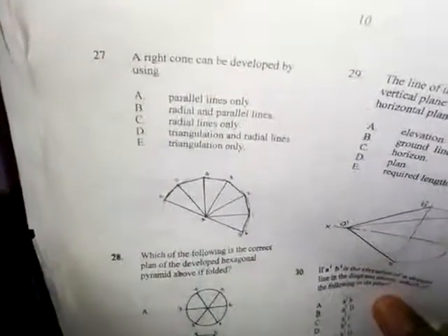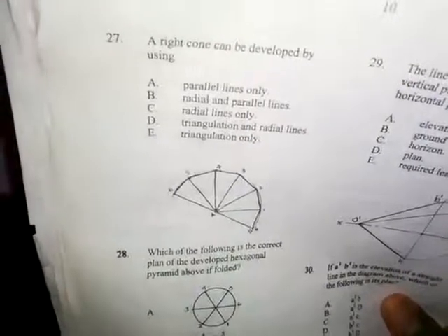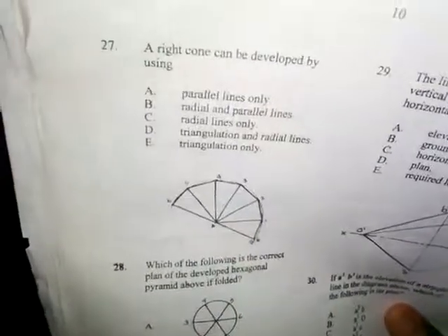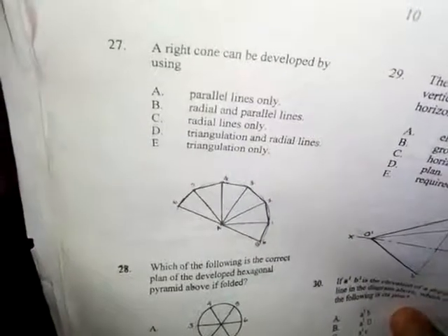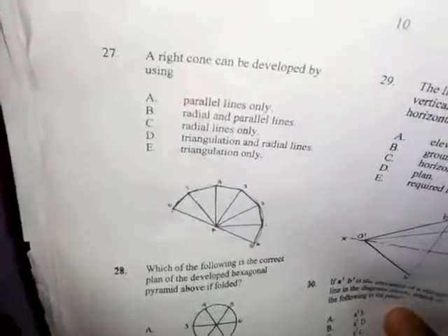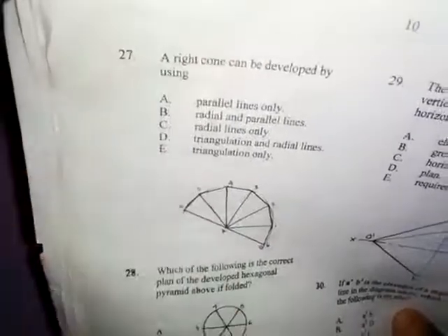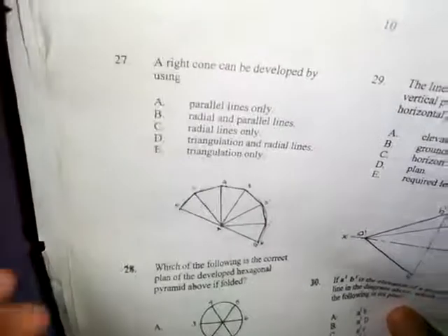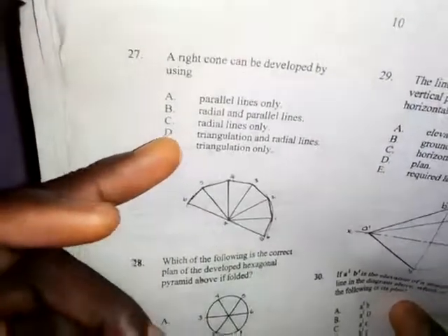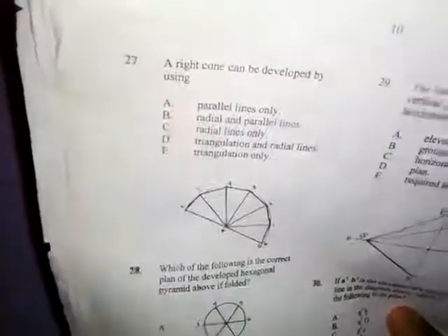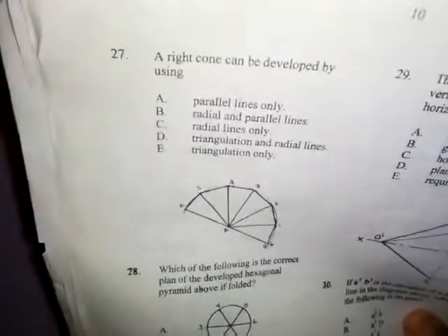Then question 27. A right cone can be developed by using radial lines only. If you are to develop a right cone, you have to make use of the radial line method only. Parallel lines are used for the development of prisms and cylinders. Then we have radial lines and parallel lines. If we have transition pieces, we can use that method depending on the